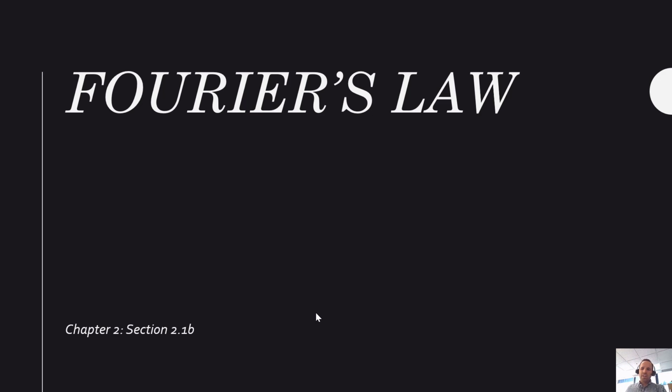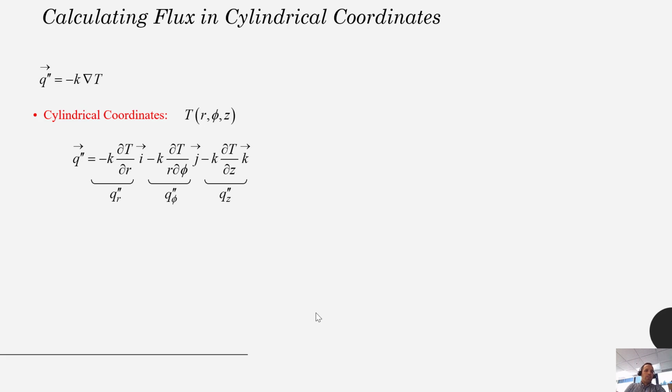In this video lecture, we're going to keep talking about Fourier's law, but now we're going to focus on radial systems. There are different types of coordinate systems. Last time we talked about Cartesian coordinate systems, where our temperature profile was given in terms of x, y, and z. But now we're going to talk about what if our temperature profile is given in terms of r, phi, and z. This is called a cylindrical coordinate system.